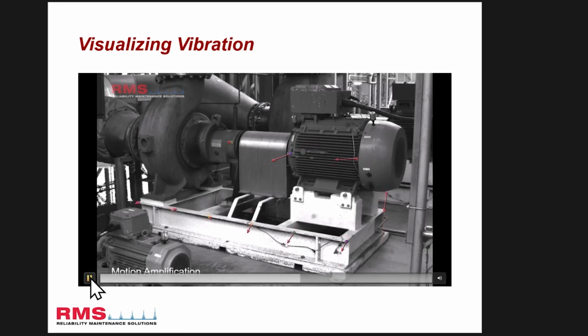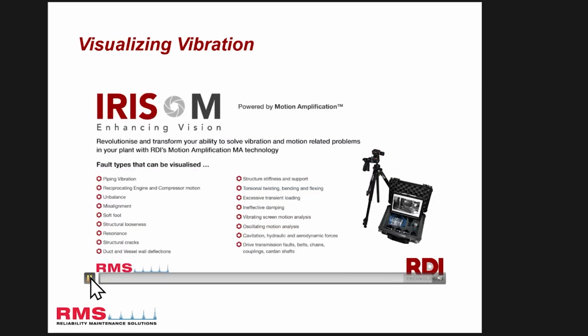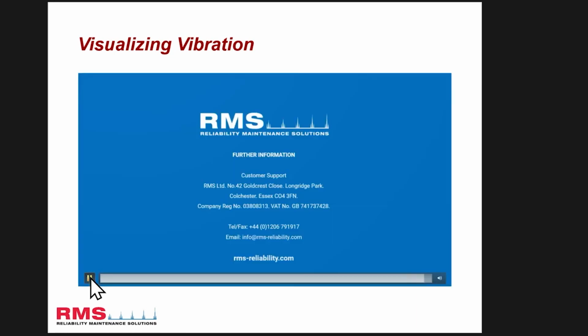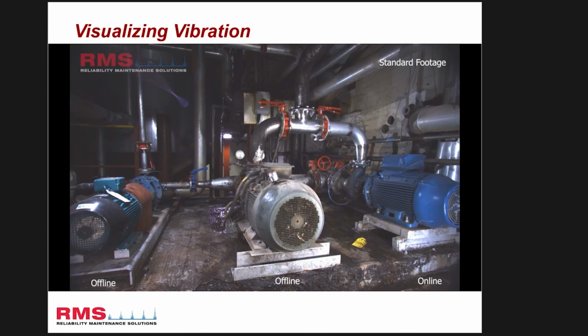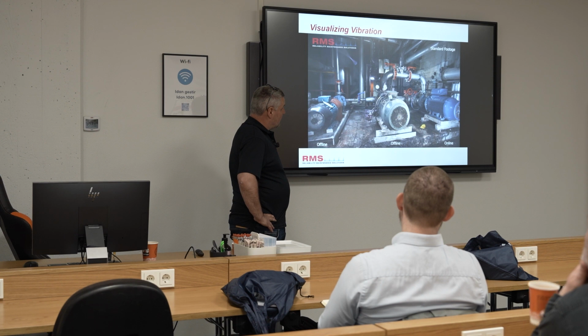You can see the vectors on there showing which way and how that machine is moving on its base. From this bed plate we can also take data plots from vibration spectrum, waveform, and all the rest of it. So there's a lot going on there. I'll come back to that in a minute because these videos go quite quick, we should slow them down. But we can take standard footage and then we can take motion amplified signatures and allow us to visualize what's